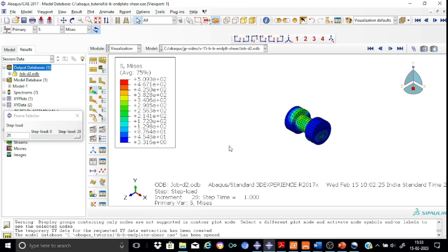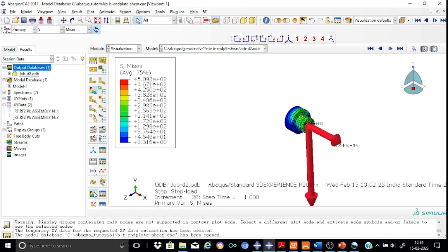Now if you are interested in finding out what will be the shear forces, please remember that if you do the calculation by hand, you won't be having any kind of tensile forces. But obviously there are out of plane displacements, and this kind of connection will obviously put the bolts in tension as well, which is normally not considered in the hand calculations. So if you want to have this, you can say yes. So we will see whether this is the maximum. Yes.